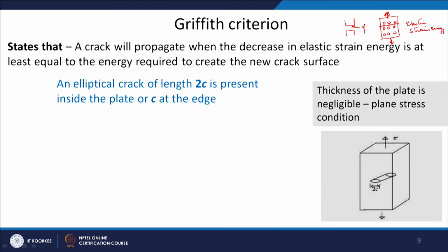So, that is what he proposed: a crack will propagate when the decrease in elastic energy, due to the breaking of bonds, is at least equal to the energy required to create the new crack surfaces. When it is equal to the surface energy of the two new surfaces.